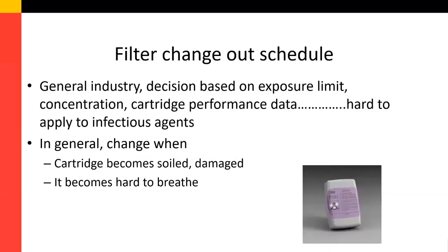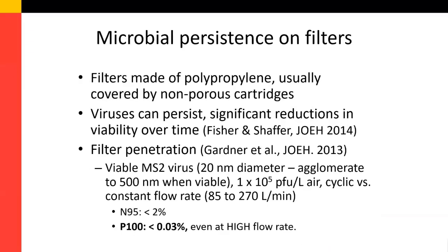So what about filter changeout schedule? In general industry, the decision to change out filters is based on exposure limits, the concentration of the toxin, and cartridge performance data, so these principles are kind of hard to apply to infectious agents. In general, the filter needs to be changed when it becomes soiled or damaged, or it becomes hard to breathe through.